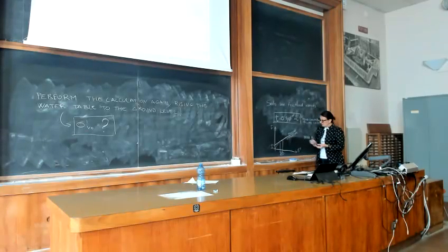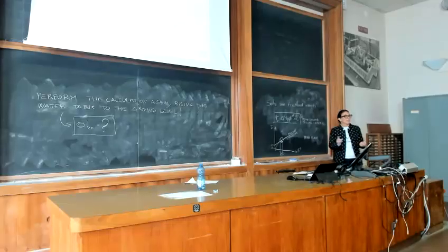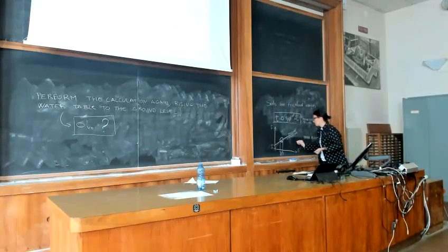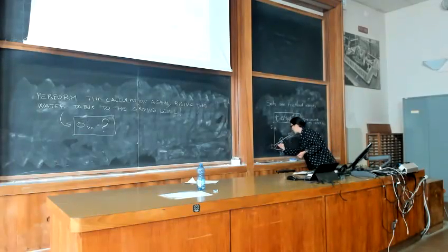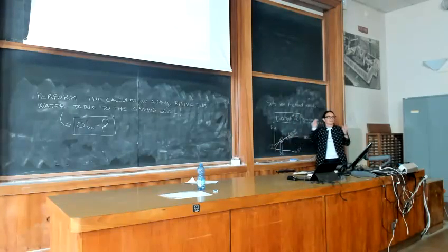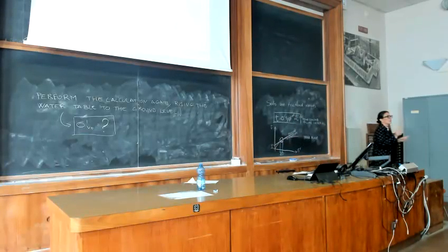But this is only an interpretation for this stress interval of a behavior which in reality is something like that. So remember that we focus on a specific stress state when we define the failure envelope for soil, and we cannot use the same parameters to define behavior for a wider range of stresses.